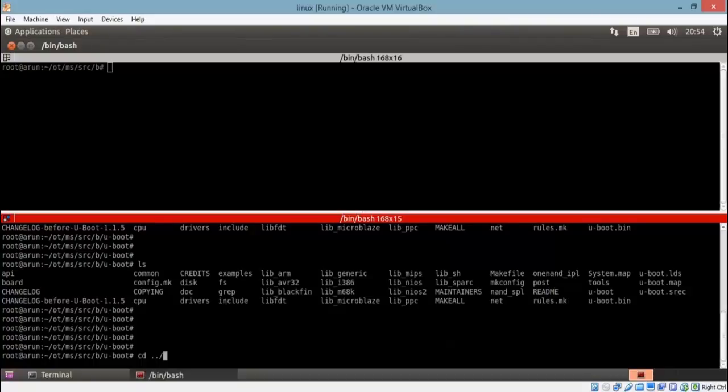There are several chips and several different peripherals. So we enable the peripheral support, support of the buses, of the devices, of the memory, almost everything. That process is called the BSP, board support package. You are writing your own U-boot for a specific target, your designed board.